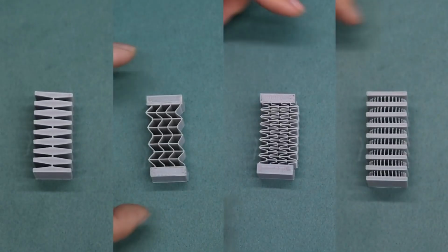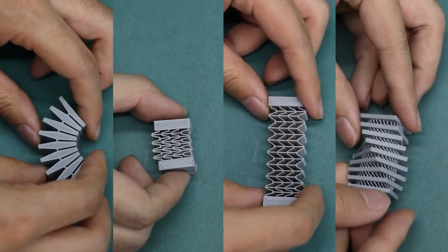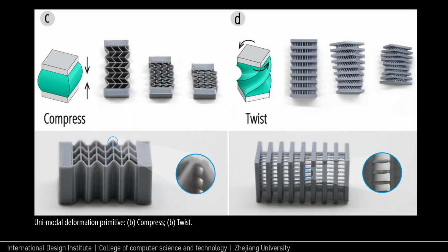Besides the tunable stiffness, we developed deformation structures including bend, stretch, compress, and twist. Though some of them seem similar to existing structures, they consist of flexible bridges and rigid parts, so all deformation only occurs on bridges, which can be well controlled with the printing parameters I've mentioned before.